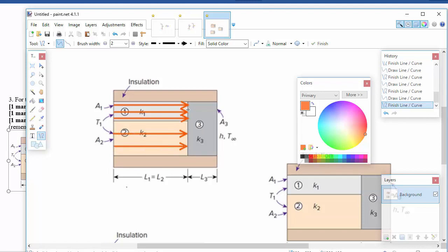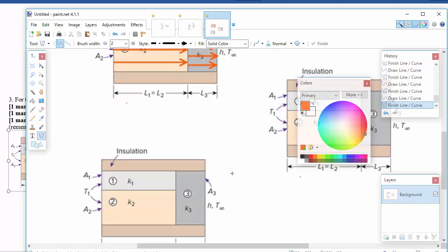And then K3, under the isothermal assumption, we'd want like 5 evenly spaced lines, just as many in the bottom area as the top. So essentially what we're saying is we've got fast heat conduction through this top part, and then slow heat conduction down here, and then it just evens out once you go over to this part, so it just jumps down immediately.